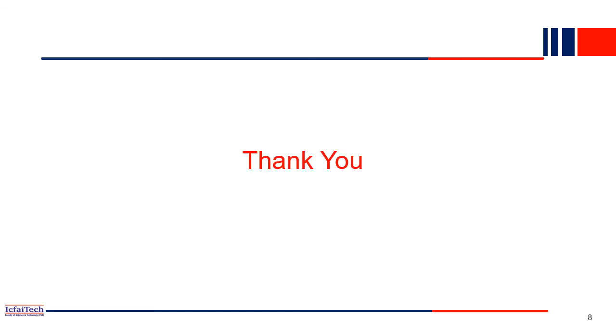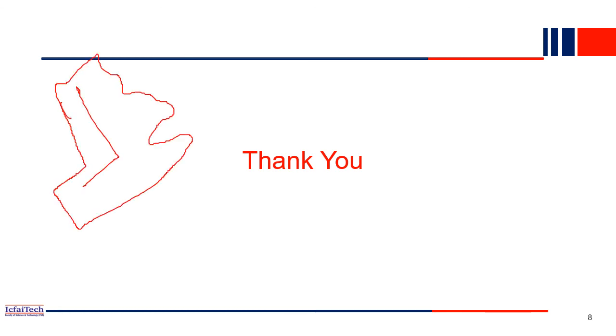So like that, basically we can design the water distribution system using the Hardy Cross method. In this lecture, what we have understood is, once you finalize the pipe layout, how pipe is going, how much flow of water is going in each pipe, what the pressure is, how much the head loss is, all these things we can compute using the Hardy Cross method. And ultimately, we can design the dimension of the pipe, the length of the pipe, all these parameters. Once this design is completed, the same layout will be given to the site engineer, who will construct the exact same dimension of pipe in the same location in the field.